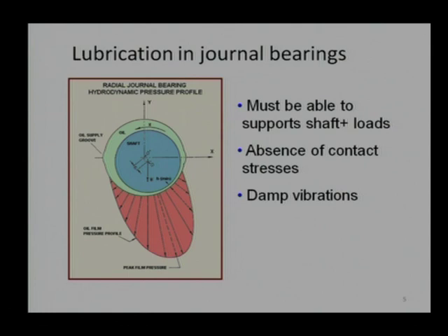It can be made in any workshop without much problem, and this bearing has a requirement of the wedge action. There should always be some eccentricity to support the load, but the eccentricity should not be equal to 1. Obviously, the shaft should not touch the surface of the bearing. There should always be some thickness, and that thickness should be greater than the surface roughness. It should not happen that the surface roughness and H are almost of the same order. In that case, this bearing will not work nicely.